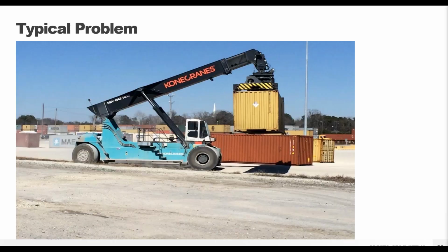So here's another typical problem that we would see. This was at a bulk material handling yard, and it consisted of these telehandlers creating really deep ruts over a soft subgrade. And the rutting develops due to that lack of confinement, so the material can just get pushed to the side, overly compacted, shoved around by the vehicle tires as the vehicles are moving back and forth. So you're constantly having to go back, regrade it, and try to smooth out the surface so that the telehandlers have the ability to move forward.